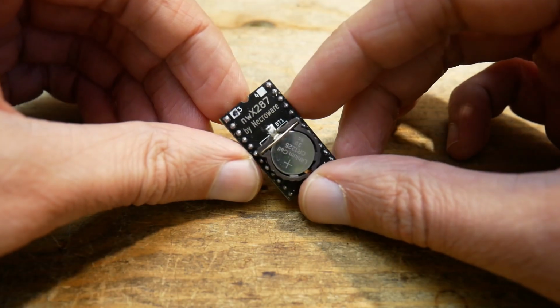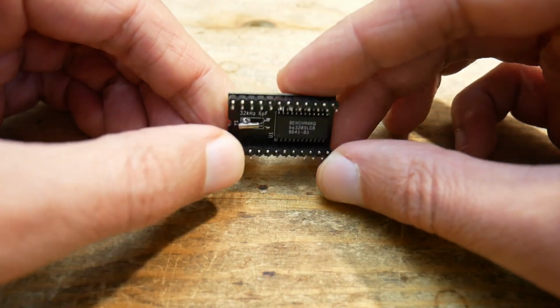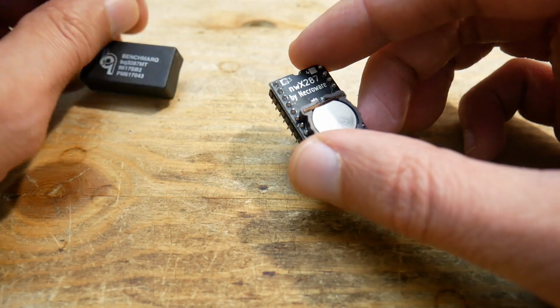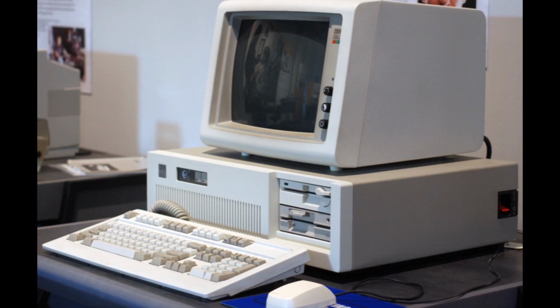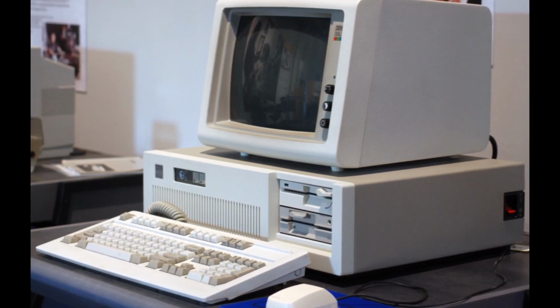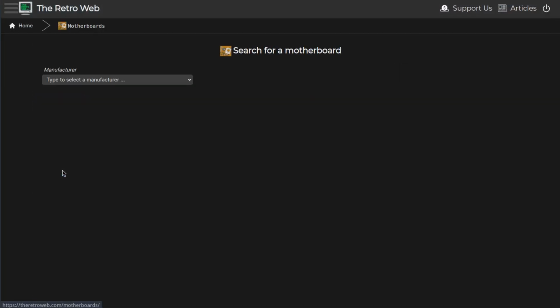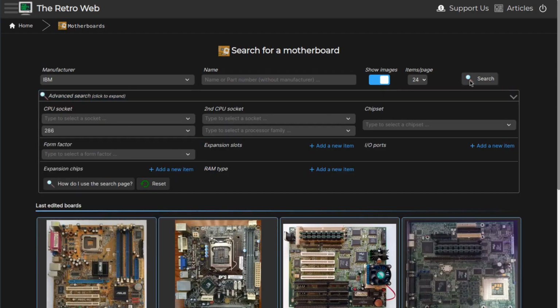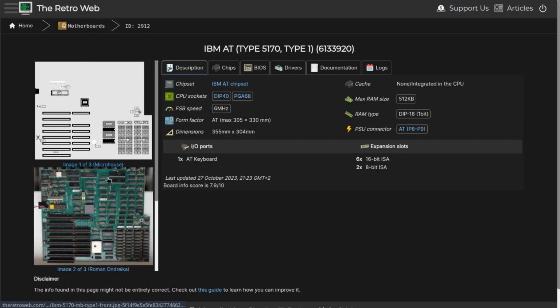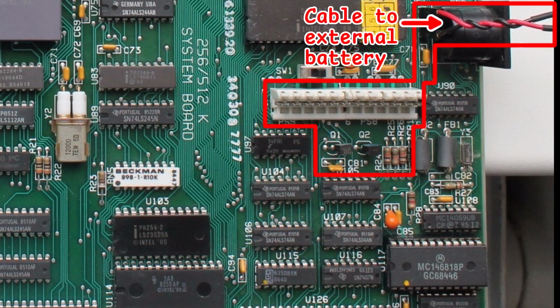First of all, let's talk a little bit about the history of the real-time clock circuit on an IBM PC and compatibles to understand better how we ended up with those black boxes at all. IBM introduced onboard real-time clock circuits with the first 286-based PC-AT in 1984, and it has been standard on all compatible systems ever since. The first implementation was used more or less unchanged up to early 486 PCs and was made of 3 circuits: the real-time clock chip, the clock generator circuit and the power supply.